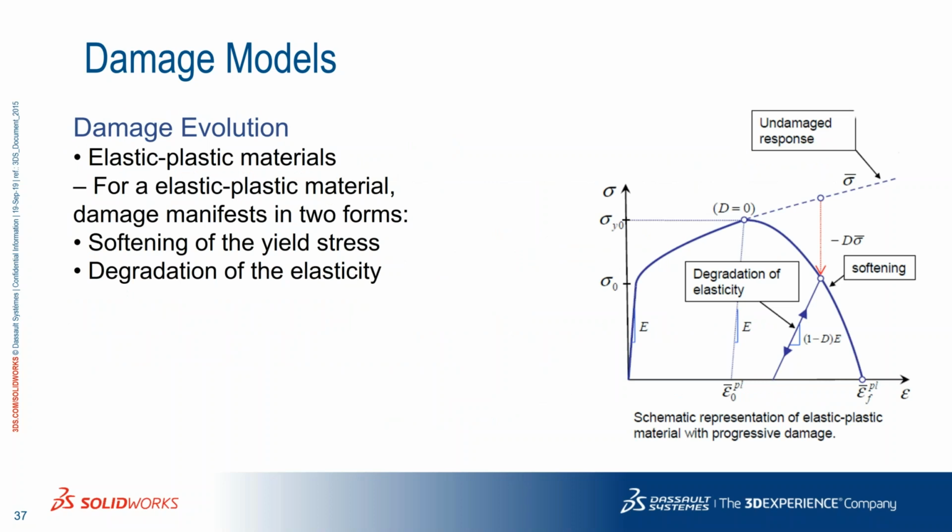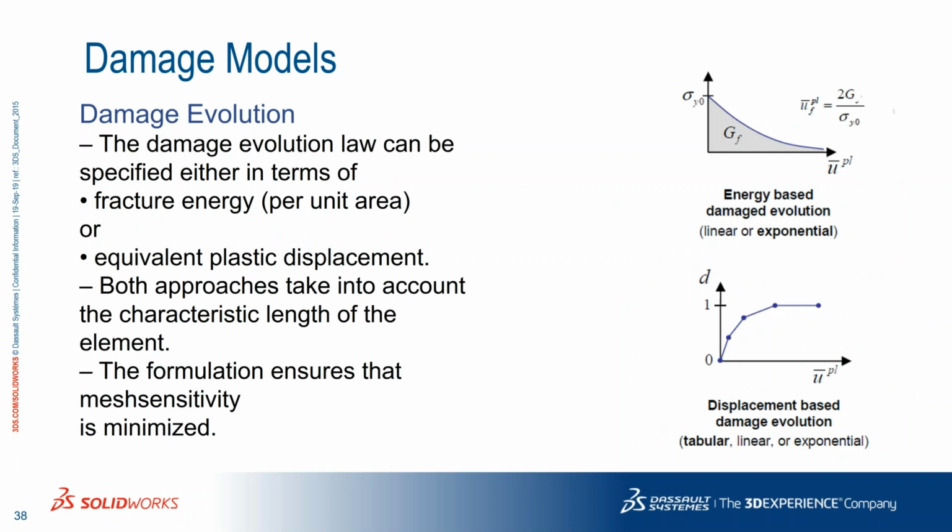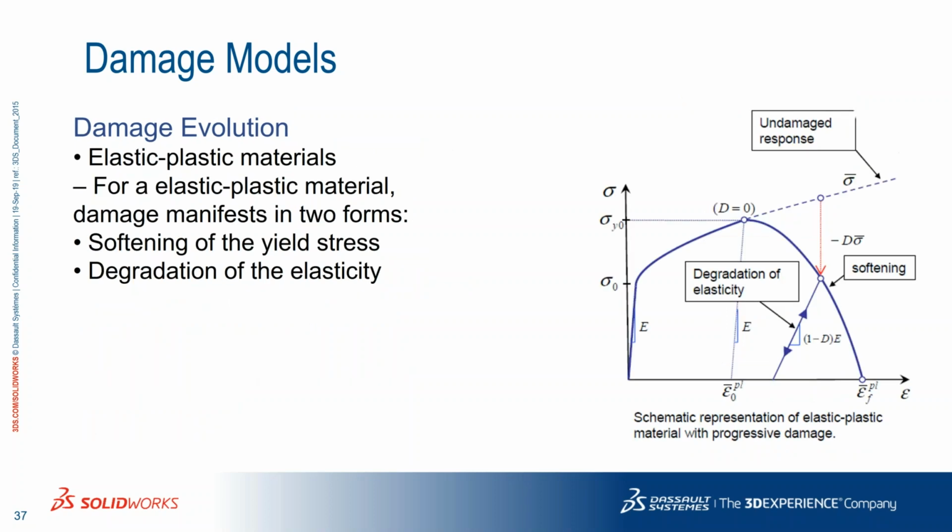Sorry. So in the damage evolution, we can use basically two ways. Here you can see the energy-based damage evolution, linear or exponential, and again this is a power law model, or just the displacement-based damage. So here we will use just the displacement that is starting to damage the element. And here you will see the evolution of the damage.